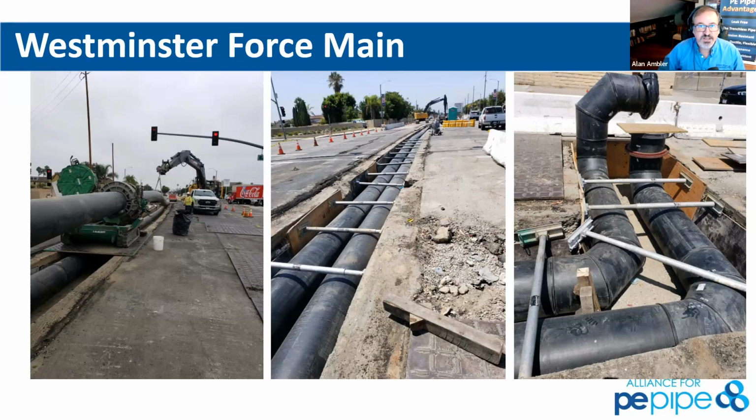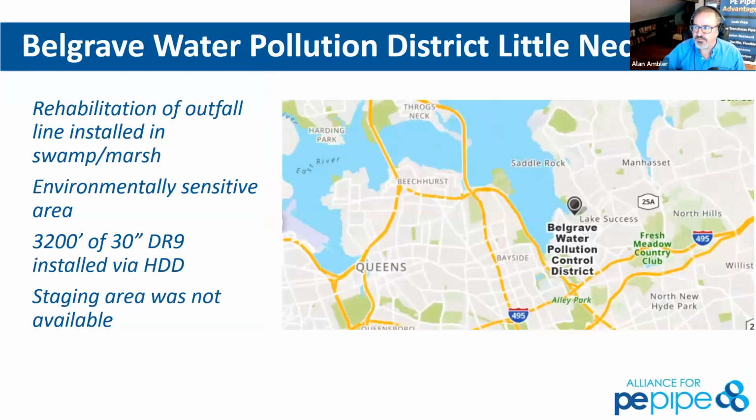So this was definitely a contractor familiar with installation of long continuous runs of pipe, their ability to be able to backfill around it, and use the pipe stiffness factor, as well as a high quality embedment material to be able to come through and make sure that they had adequate protection from any load above.